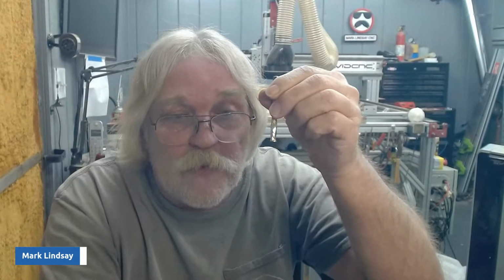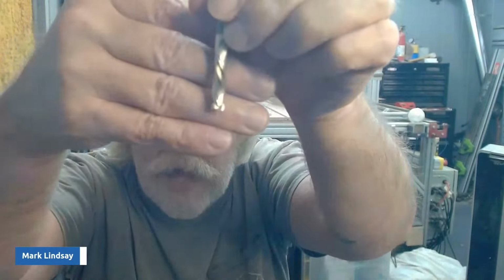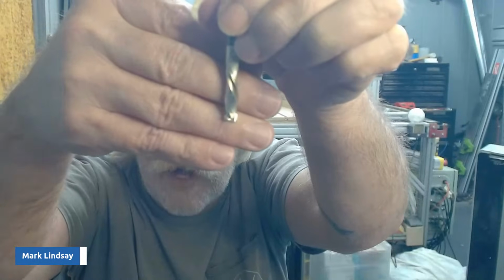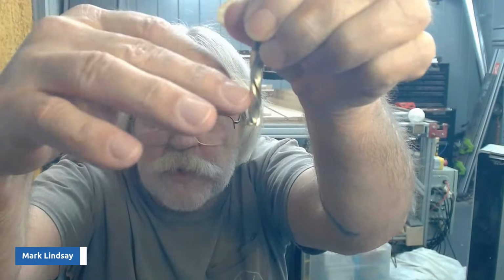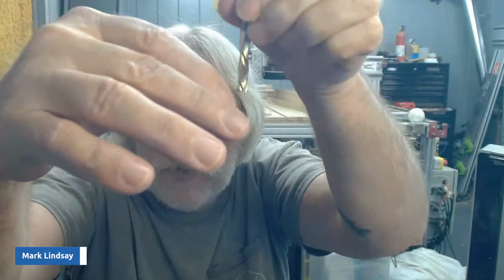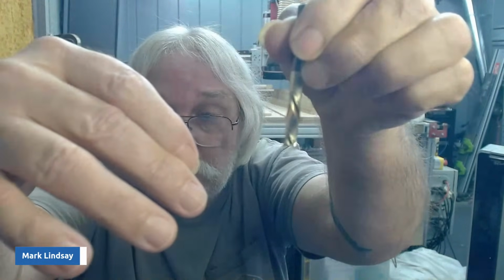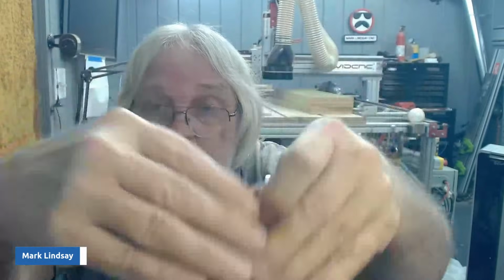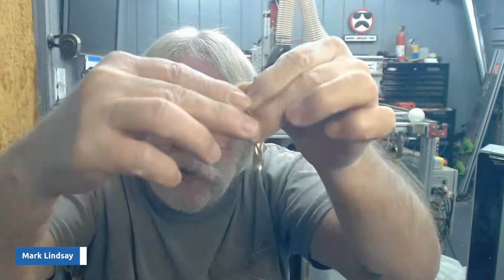The problem lies in that initial plunge. That initial plunge into the material where it first starts cutting. If you don't have that upcut portion right there at the bottom buried below the surface of the material, it's the same as using an upcut bit. And you're going to get chip out on top. So for that first pass, it has to go in. Then you can worry about cutting the rest of it.